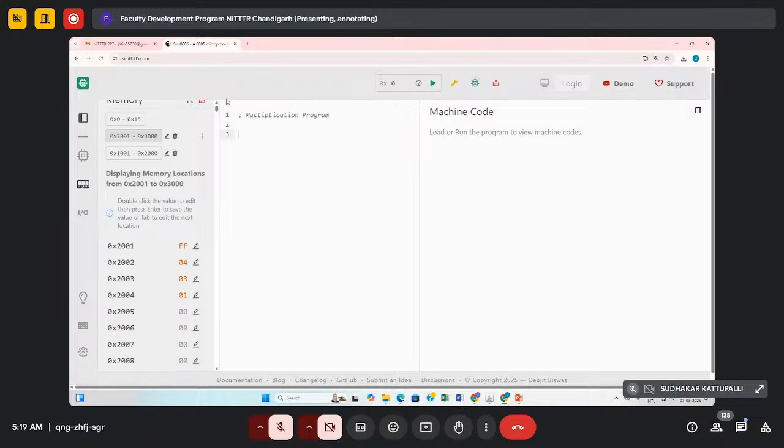Successive addition is what we'll do. MUL is there in 8051, not in 8085. So in 8085, you don't have an instruction to directly multiply two numbers. So what we'll be doing is multiple addition, successive additions basically. We'll develop some counter and do successive addition.